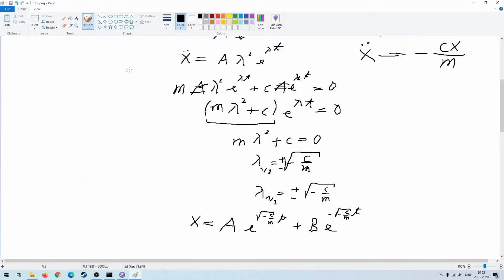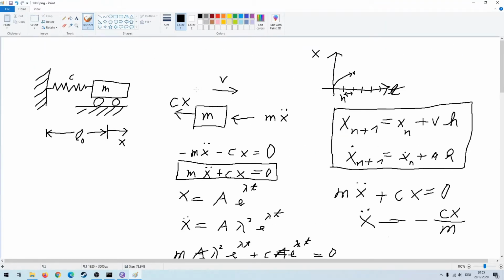But of course we need a new equation to describe our system, because right now we only have the spring stiffness. But if we have damping, damping is always in the opposite direction of the moving mass. So that means that damping is in the opposite direction of our x-coordinate, and damping is also dependent on the speed or on the velocity.